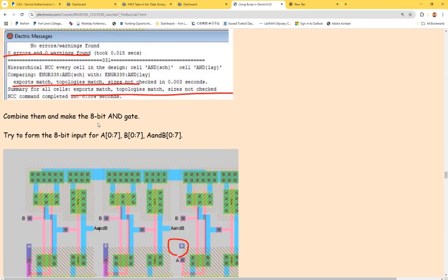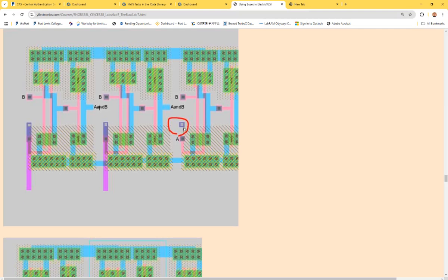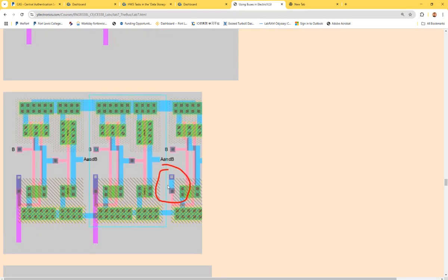And this is the layout. So every time you introduce the metal tool, you want to place the little metal 1 to metal 2 via here first, and then click that specific metal tool in the toolbox, and then do the connections. See here, metal 1 to metal 2 via.